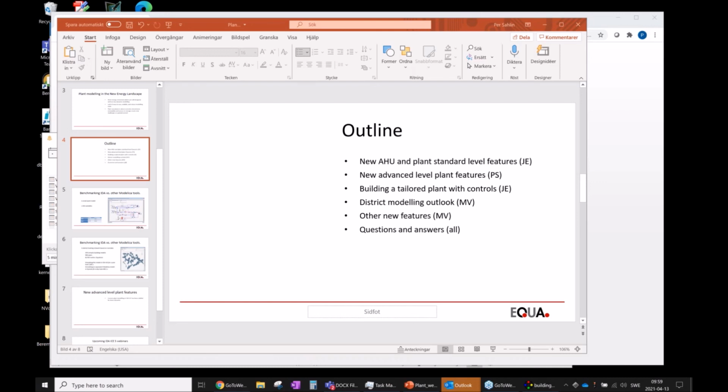When it comes to the borehole, it's a very long story actually, but the most commonly used borehole model is using these G functions that we are not using. G functions are actually a severe simplification in many ways, which the IDA model does not suffer from. So we're not trying to mimic results that come from programs that use G function approaches, but rather more measurements and more detailed physical models.